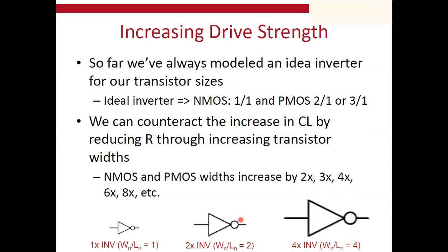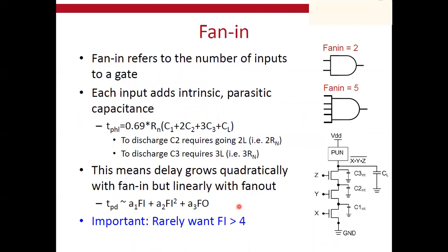But what will happen here is you multiply the overall capacitance seen by the inverter by 4, which will contribute to the overall propagation delay in this step. So this is a very important one.